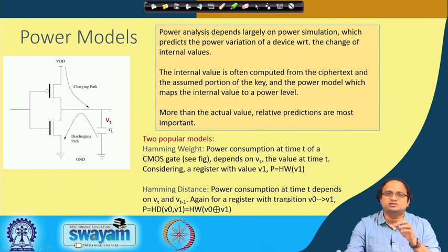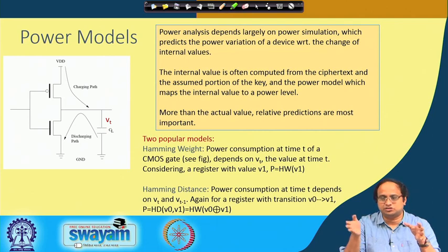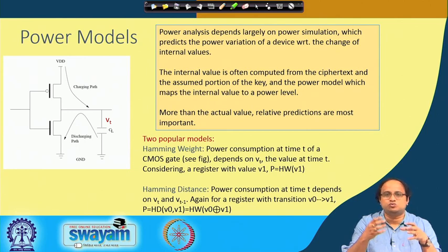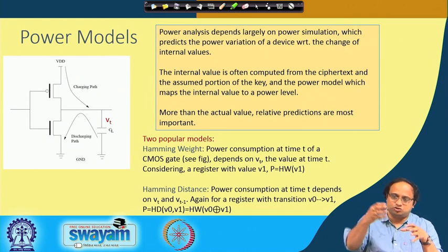One of the reasons is that in certain categories of implementations, as we know in CMOS, particularly when we talk about dynamic CMOS, we have certain circuits which get pre-charged. So, there is a pre-charge stage followed by an evaluate stage. In the pre-charge stage, you can either charge a state to 0 or charge a state to 1.